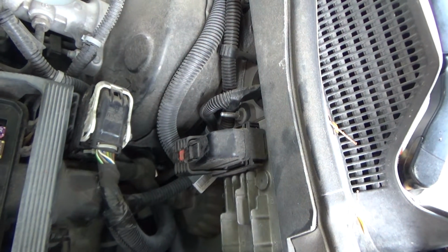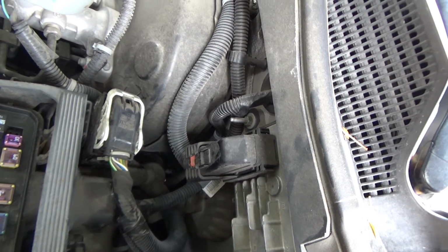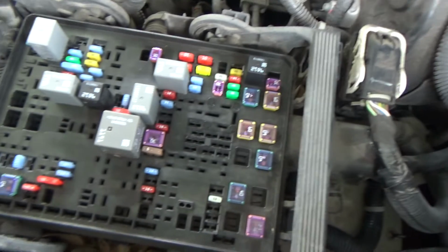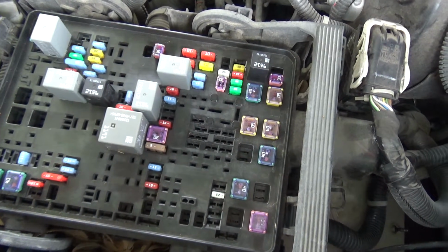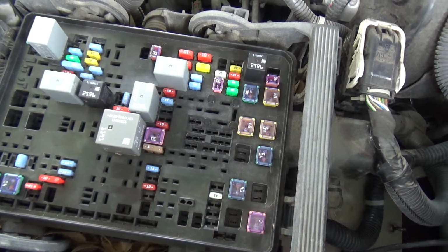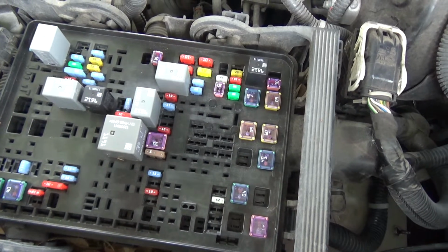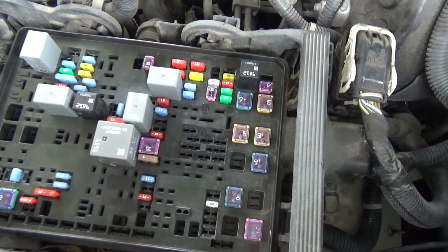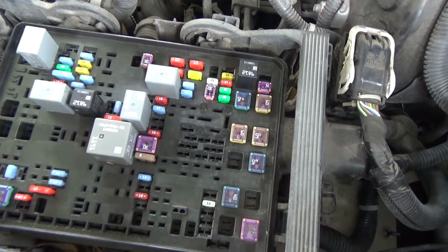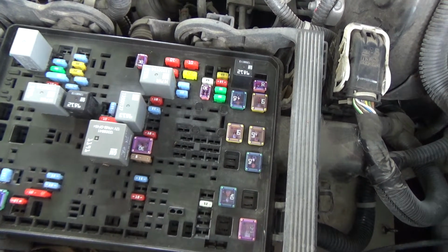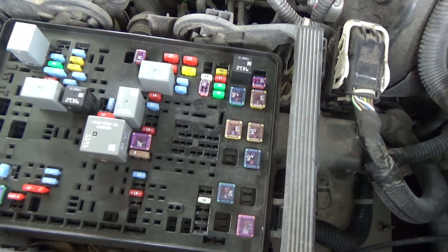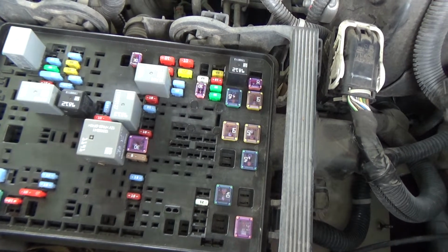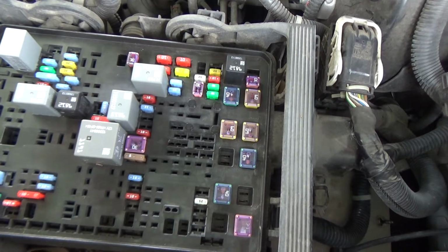I don't really want to poke holes in them, so I don't think I'm going to bother with that, simply because, like I explained over there, if the high-speed relay was going over to the high-speed contacts, then the low speed should stop working at that time. The wipers shouldn't stay on low speed.